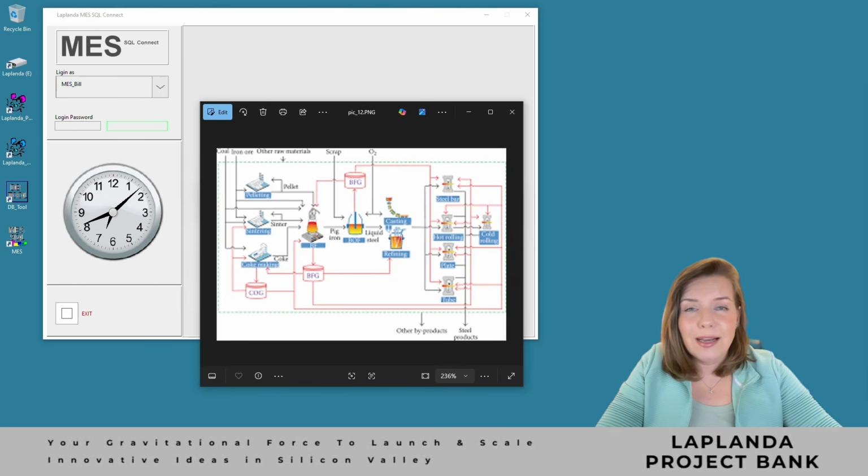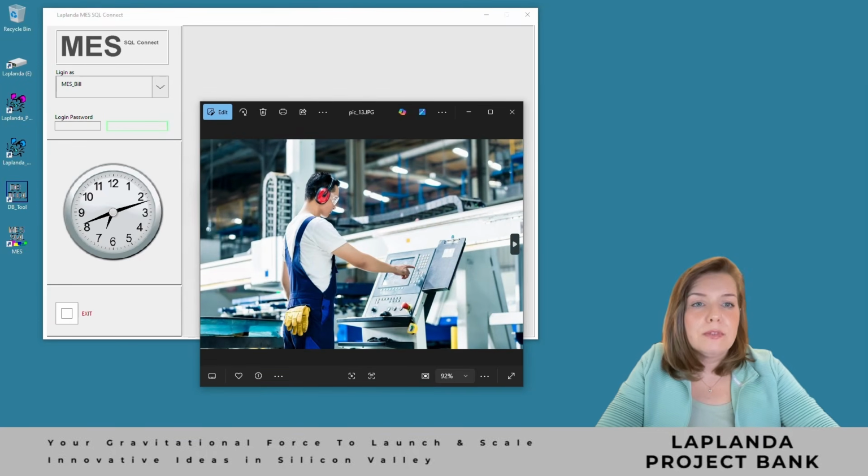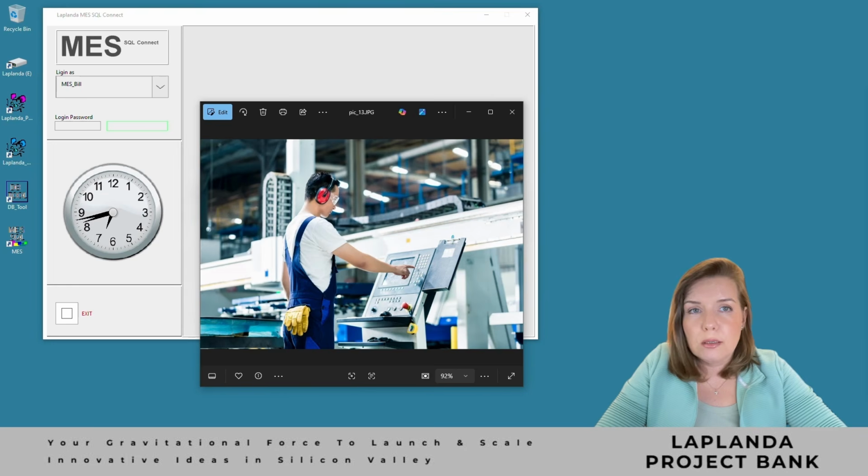The next thing we need to consider, and this is a very important point in organizing any production process, is the operator's work and the operator's workstation. Depending on many factors, whether it's a workshop, a production line, or a clean room, the operator may be allowed to sit or may need to work standing. We must decide whether a touchscreen display is appropriate or if a button-based interface is better. If a touchscreen, what size should it be? Will it still function properly if the operator is wearing rubber gloves? If there is a separate keyboard, how will it be protected from dust if such conditions exist? And there are many other factors, including labor regulations, fire safety requirements, and various certifications.